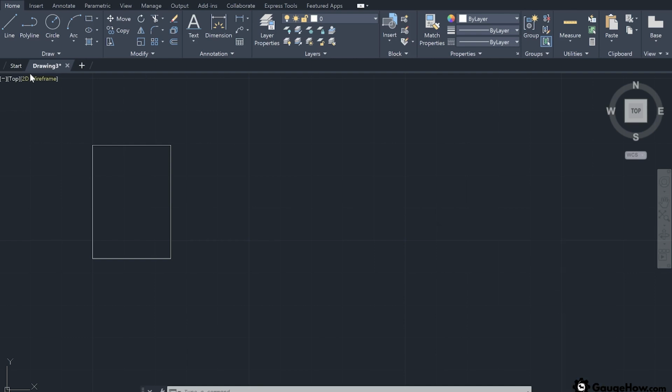After enabling these, I will again select the line tool, and now I will move the cursor to the right hand side and top corner of the rectangle, and here the endpoint snaps easily. Once I move the cursor over here, clearly note that I have not clicked at this point. Now I will move the cursor from this endpoint towards the right hand side. You will see that one reference line appears indicating the horizontal line passing through that endpoint.